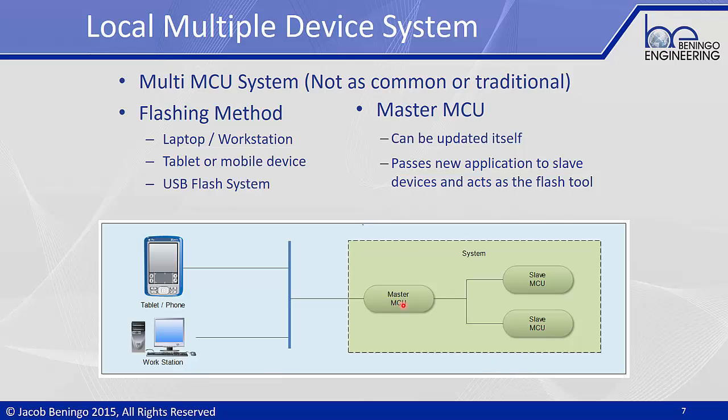Then what we end up having is a bootloader on each of the slave MCUs as well as the master MCU. We then perhaps have the same type of environment where we're going to walk up with a workstation, a laptop, or a tablet. We're going to physically connect to the master microcontroller. We can then have the opportunity to update the master microcontroller or to have the master microcontroller act as a pass-through so that we can update the firmware on the slave devices.